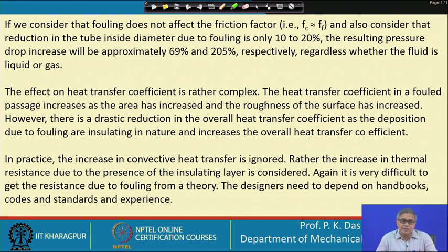If the passage is reduced and the mass flow rate is kept constant, that amounts to increasing the velocity. If we increase the velocity, obviously the convective heat transfer coefficient will increase.